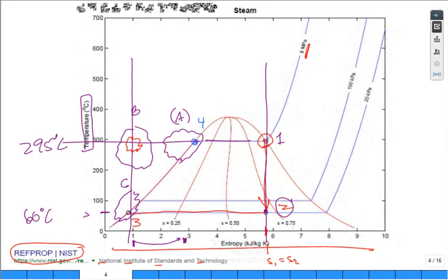Somebody asked a question. They say, hey, last lecture, state 4 was right there. Yeah, state 4 was right there for the Carnot, and state 3 was right there on a straight line below for the Carnot vapor power cycle. But now we shifted away and we talked about the pump that had this job of taking 3 to 4, an unhappy pump. A pump that doesn't really exist. You cannot buy it. It's a fool's errand to try and design it.